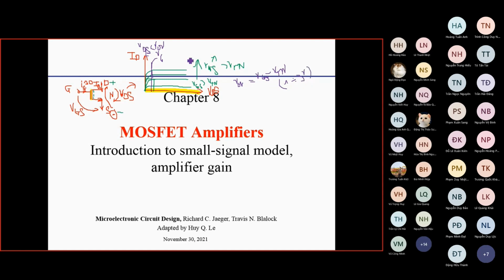So on the left side, the transistor is in the triode mode, when it behaves as a resistor, with the resistance given by the slope of this curve. This part of the characteristic curve can be approximated as a straight line. And of course, the higher the VGS, the steeper the slope here. That means the lower the resistance, right?